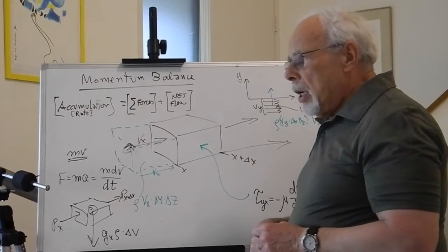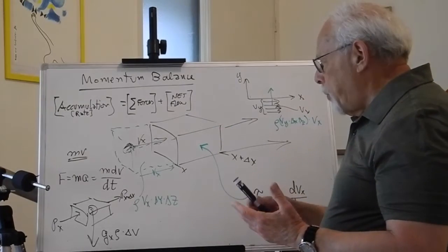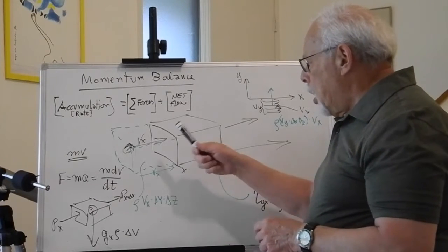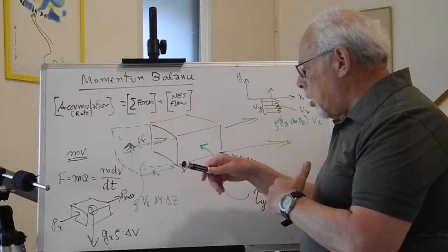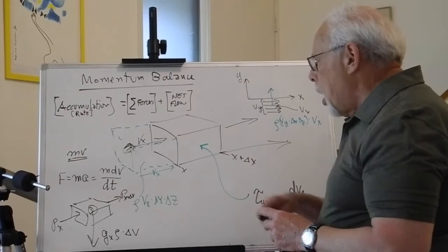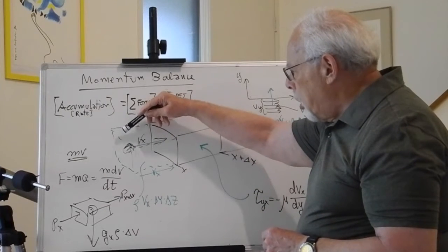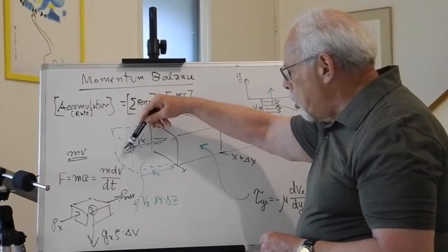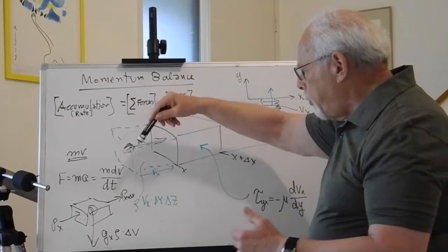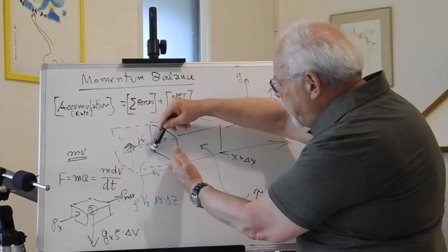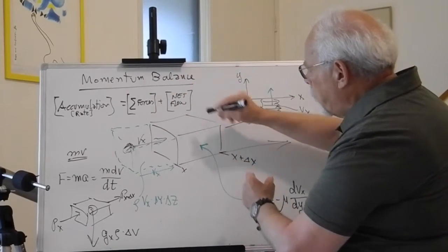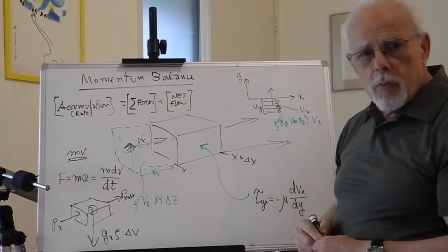Net flow: first of all, when we are looking at one axis, x, we have fluid that has a velocity vx flowing through this face, and then some fluid flowing out of the counterface here, which is not drawn.